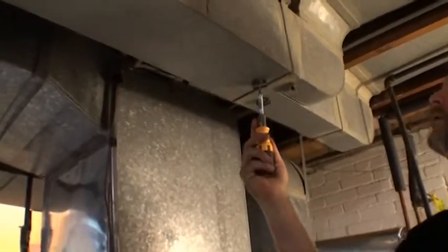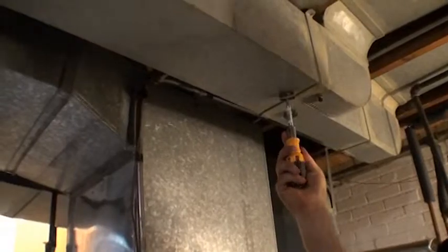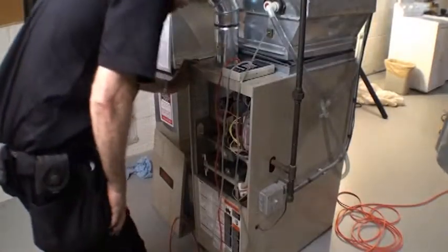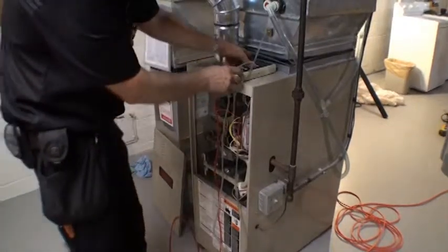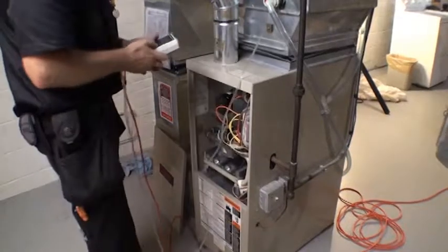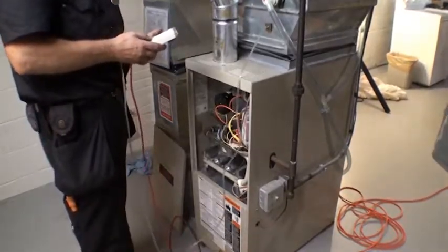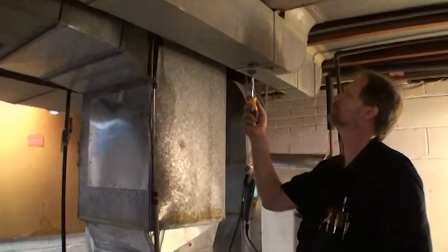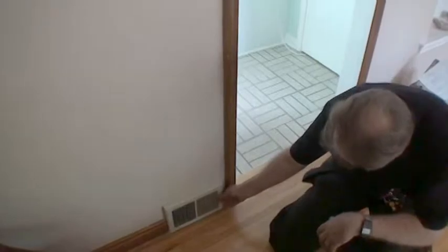Confirm all vents are open and clear. Call Community Action if any changes must be made to the duct system. Perform the static pressure test to ensure the furnace is within the range indicated on the furnace data plate. If the static pressure is not within the specified range, investigate to find out what duct alterations are needed to correct the static pressure. Call Community Action if any changes must be made to the duct system.